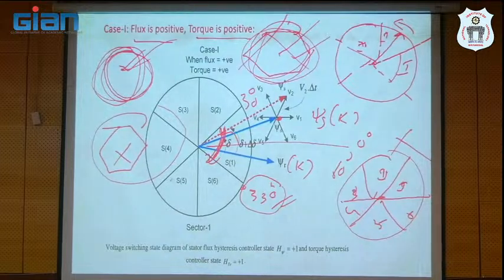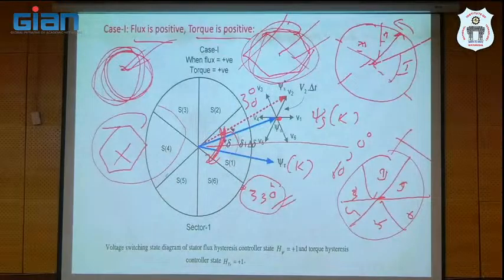So how many points are very crucial in DTC? First, you need to take care about actual system behavior. With respect to actual system behavior, the stator time constant should be good compared to the rotor time constant. This is essential. While purchasing the machine, you need to take care about the X/R ratio of the stator winding and the X/R ratio of the rotor winding.